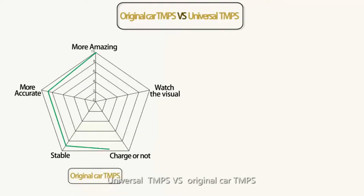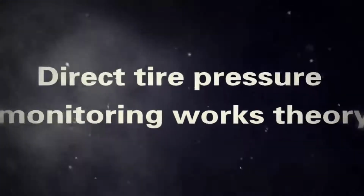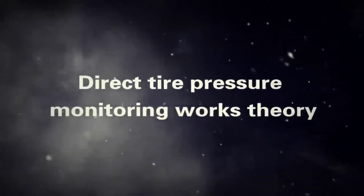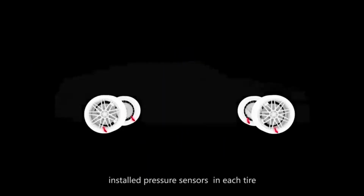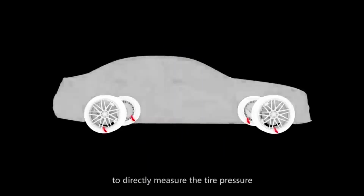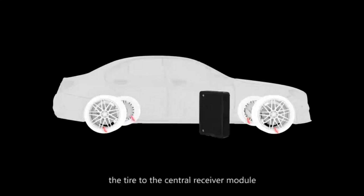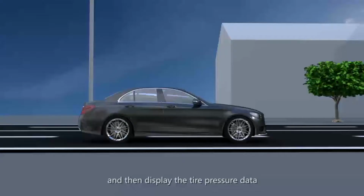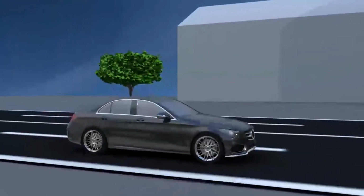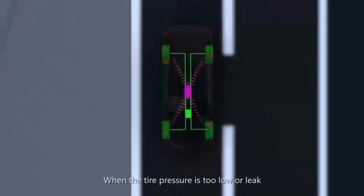Original car TPMS versus universal TPMS. Direct tire pressure monitoring working theory: pressure sensors are installed in each tire to directly measure the tire pressure. Next, the pressure information is sent from the tire to the central receiver module by wireless transmitter, and then the tire pressure data is displayed. The system automatically alarms when the tire pressure is too low or there is a leak.